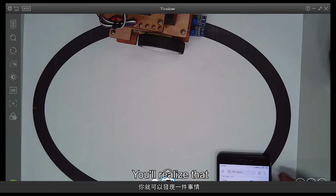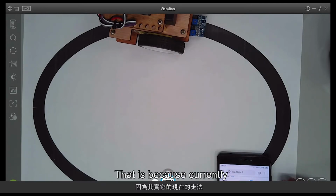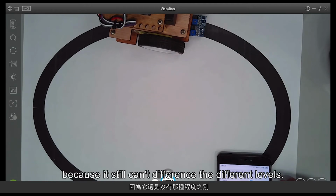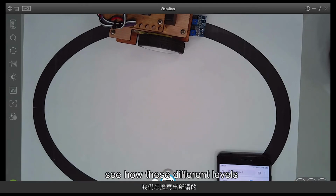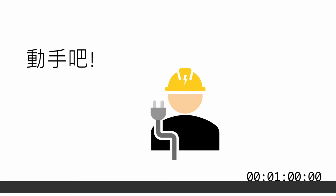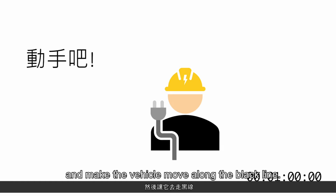You'll realize that its range of motion still resembles the digital method. This is because currently, it's only referencing the analog reading but with motion using digital. Because it still can't differentiate the different levels. Let's move on and see how these different levels are written for the motion using analog tracing. You can try this out yourselves. Read the analog reading, then perform a simple evaluation, and make the vehicle move along the black line.